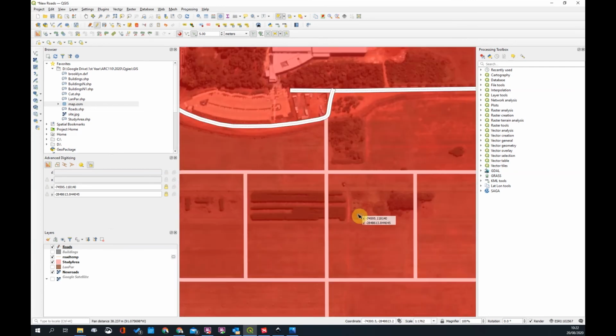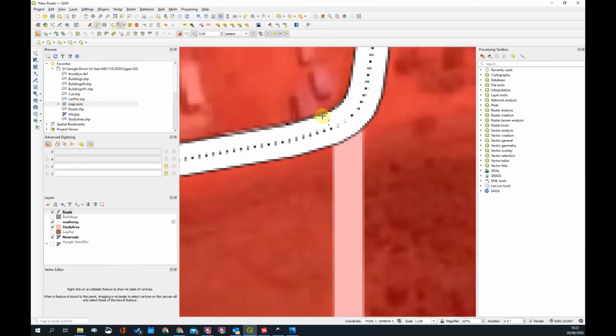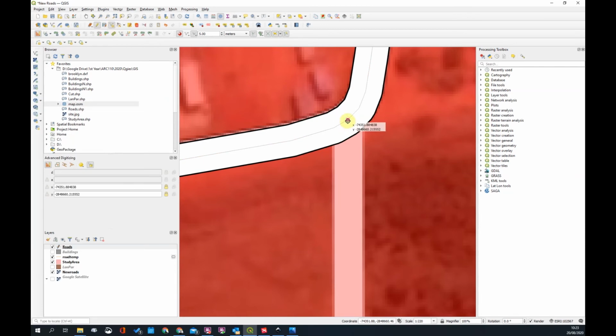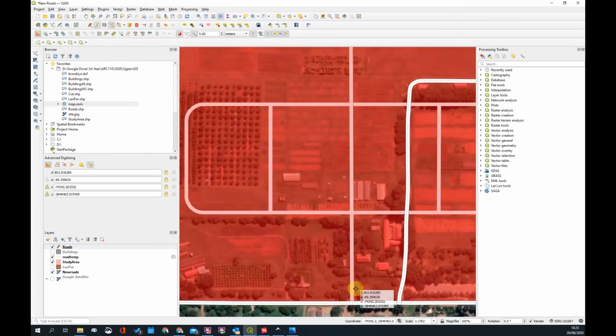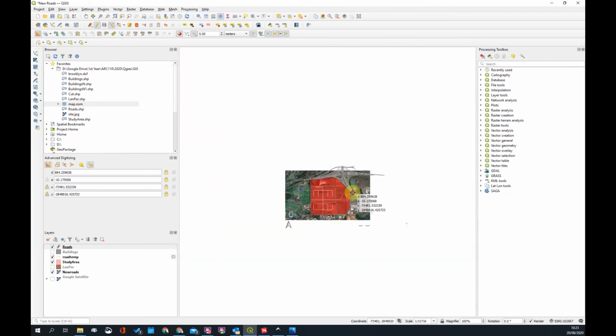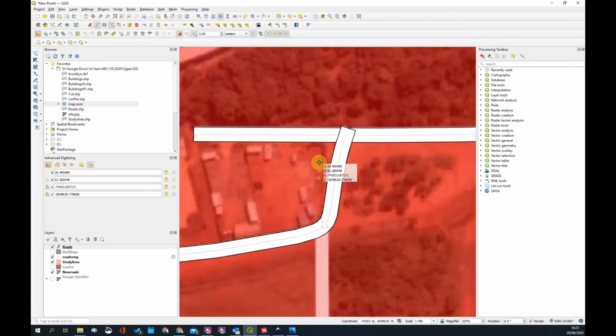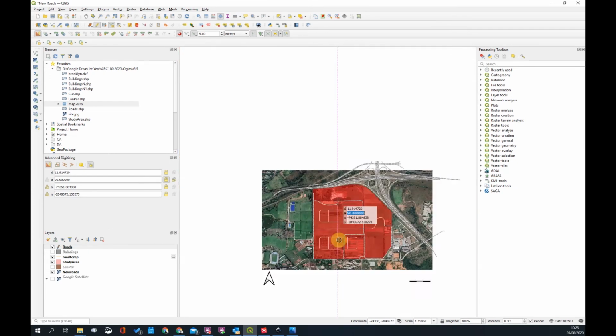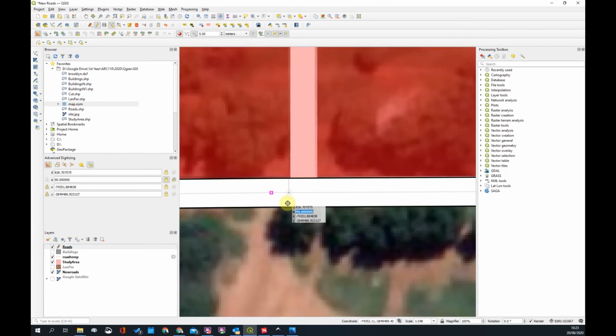So just start creating a feature. I'm going to create a road. Here, to allow me to snap to certain objects, I'm going to snap on this endpoint and come down vertical. I've got my advanced snapping tools on. If I zoom in and you want to snap vertically, you press Ctrl A, and it'll lock it on that vertical axis. So I'm going to come right back to there. Okay, that's my first road. That will work fine.